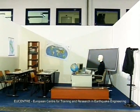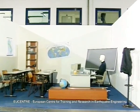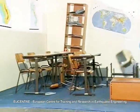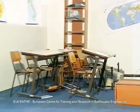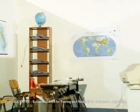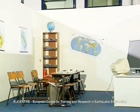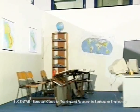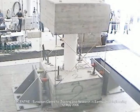Earthquake engineering, such as other experimental sciences, strongly relies on lab tests. For example, in order to study the behavior of a building during an earthquake, to test its capability to resist a seismic event, or simply to tune a model, a very straightforward tool is represented by dynamic simulation. A scaled version of the structure, usually referred to as specimen, is put on a shaking table, moving according to a previously recorded seismic wave profile.